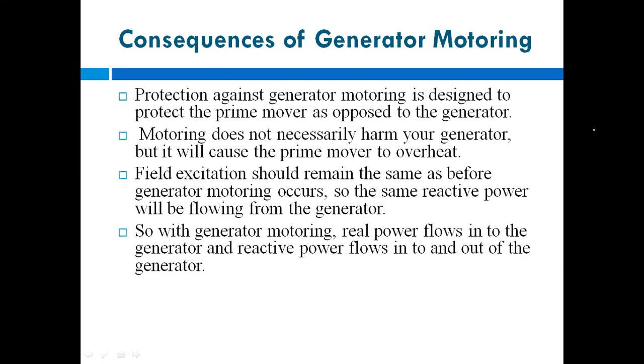So here the same concept applies. This motoring does not necessarily harm your generator, but it will cause the prime mover to overheat. Then field excitation should remain the same as before. Whatever supply we are giving to the field winding, that field winding excitation should remain the same as before generator motoring occurs.